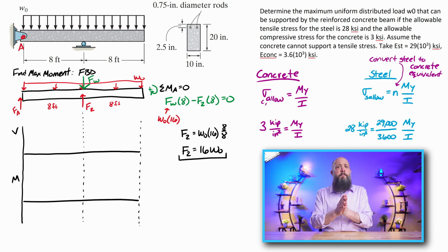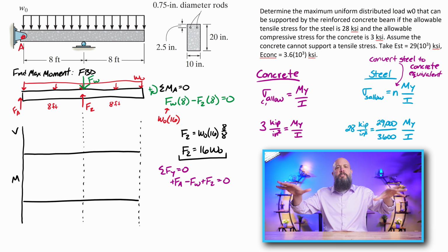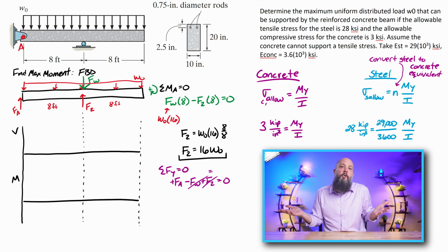So essentially the roller joint is holding the entire force. And the pin at A is just sort of there for balance because the distributed load is basically perfectly symmetrical over the roller joint. So my shear diagram starts and ends at 0. Just every shear moment diagram starts and ends at 0.